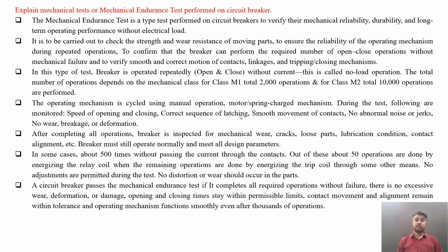Explain mechanical test or mechanical endurance tests performed on a circuit breaker. So actually this test can be asked as mechanical test or mechanical endurance test. Both are one and the same. The mechanical endurance test is a type test performed on circuit breakers to verify their mechanical reliability, durability, and long-term operating performance without electrical load.